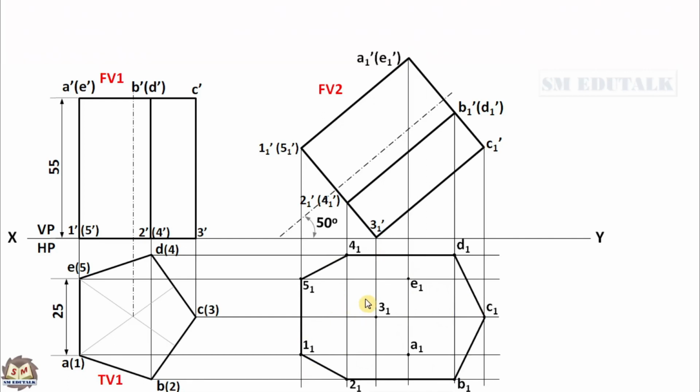To do this, the observer is standing in this position to look at the object to get the top view, and his eye rays are passing orthogonally to the plane like this. Now he can see the top base and this rectangular face. That is, the top base is visible because his eye rays are passing over this line.